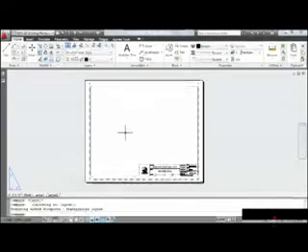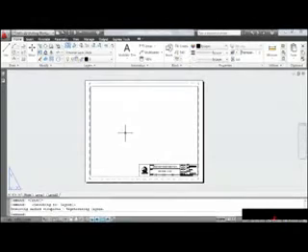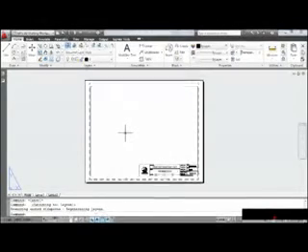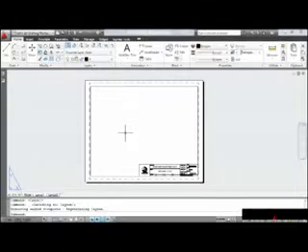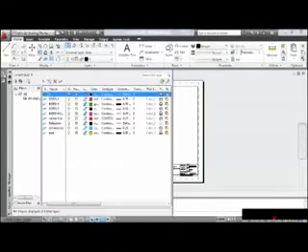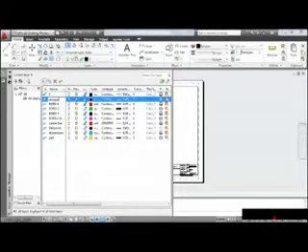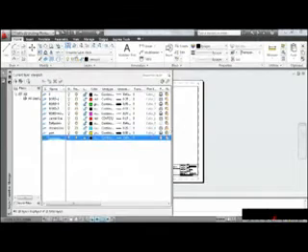Layouts sit on top of Model Space. So if I want to see my part, I need to cut a hole in this layout. This hole is called a viewport, and if I'm going to create a viewport, I need to put it on a layer of its own. So I'm going to open up the Layer Properties Manager, and I'll click the new icon. I'll call my layer Viewport, and then I'll click the green check to set this layer current, and I'll return to the drawing.